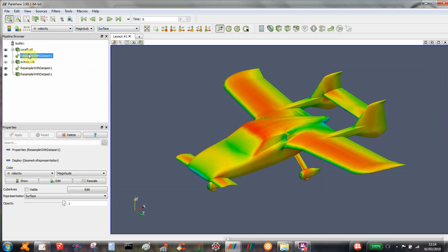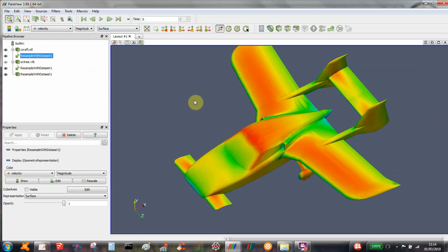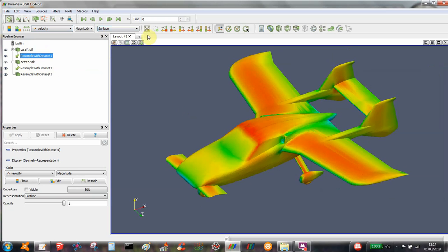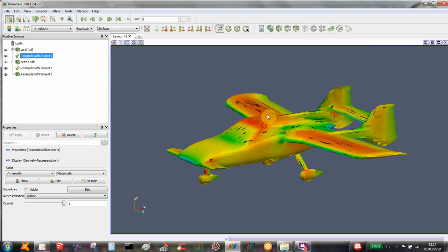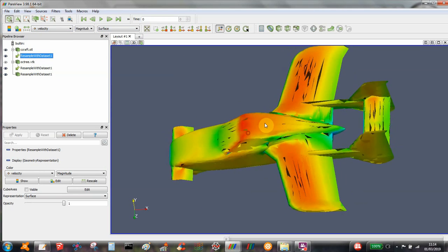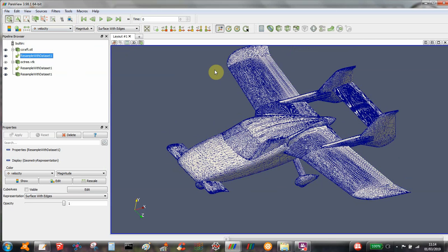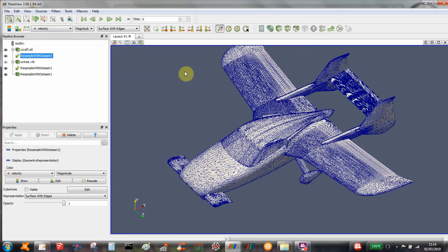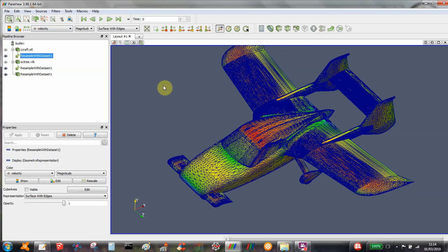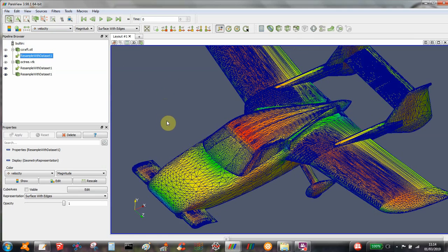so yeah, once you've resampled onto the STL file, then you literally get the flow solution mapped onto the STL file, which is sometimes a bit cleaner looking than when you use a distance field. But beware, because sometimes it will look worse if the STL file is quite coarse, because it's interpolating the flow solution onto an STL file, which, I mean, this one is not too bad.